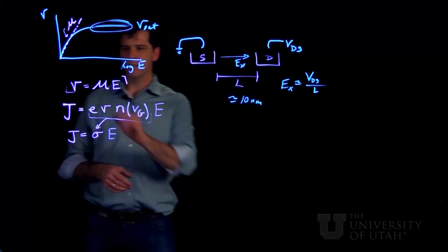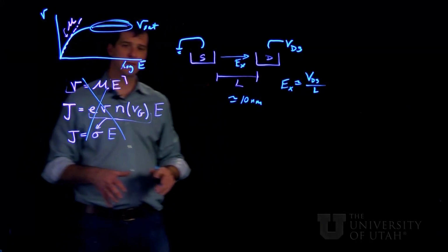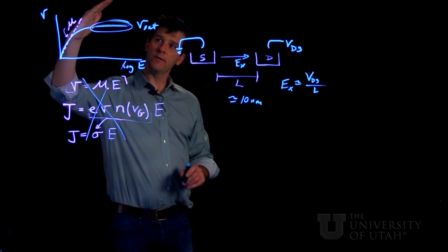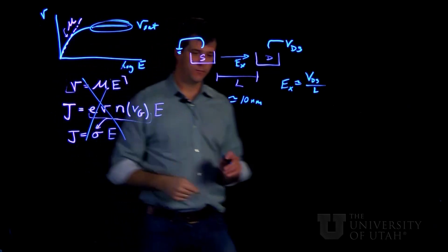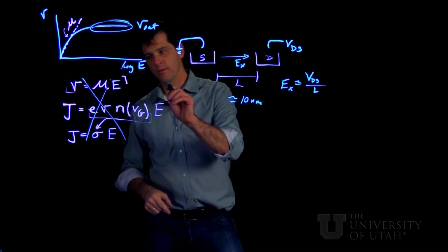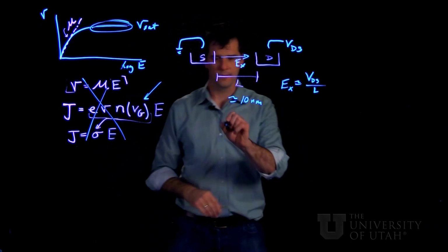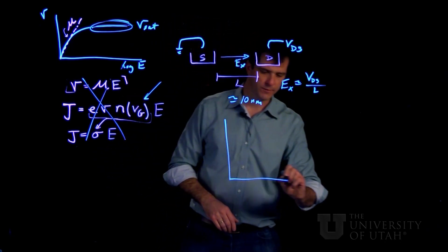What this means is that Ohm's law no longer applies, and we are getting the carriers to go at a slower velocity than they would have otherwise. That means that the total current being pushed is going to be decreased for a given voltage.